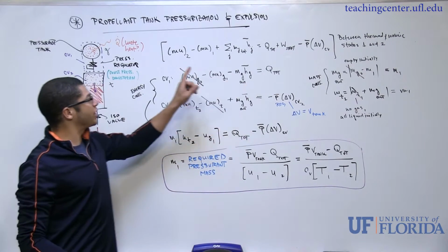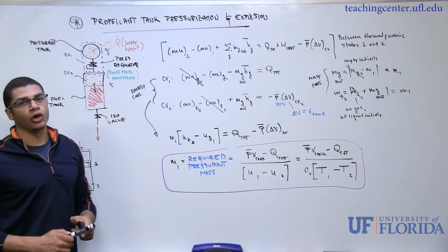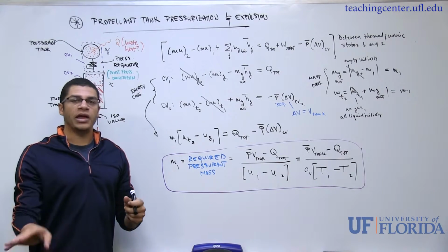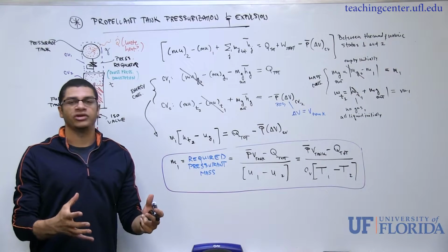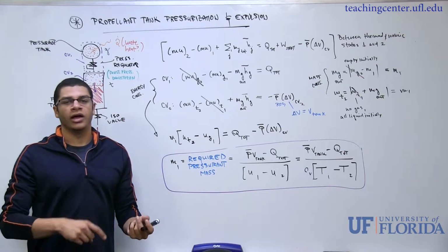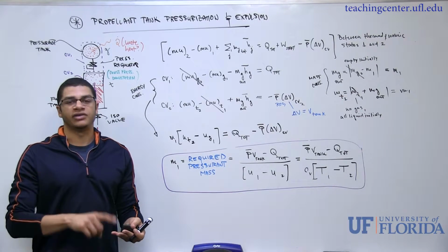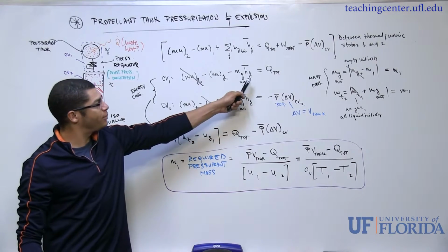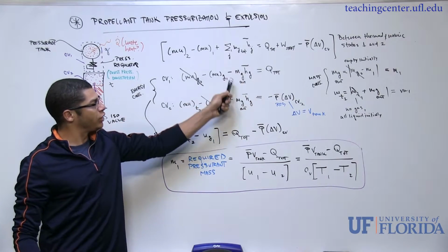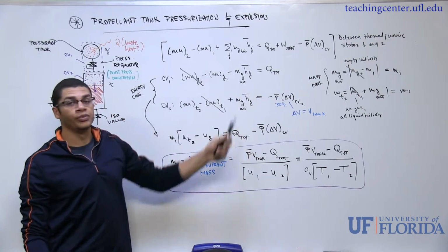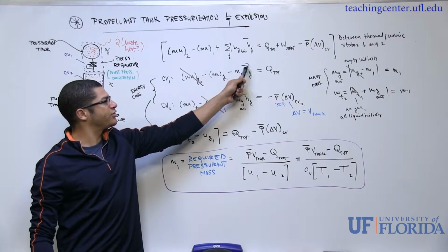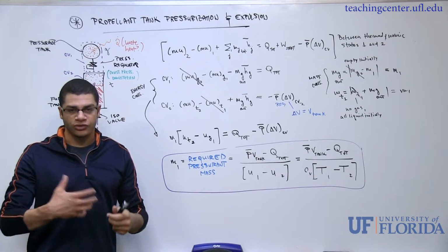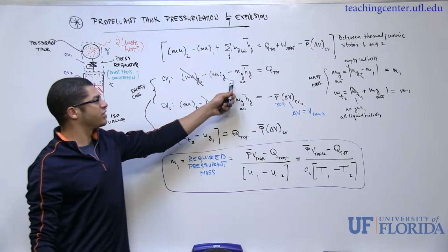So we do have to realize here that, again, this is a constant volume tank, and we're expelling mass, so the energy in the tank is going to be dropping with time, so its pressure, temperature, etc. are going to be changing. So we would expect the outflow of enthalpy to be changing as well. But we're going to take some intelligent average between the initial state and the final state, and that's what I've signified here.